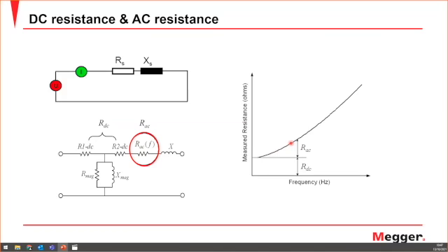That's exactly what happens in reality. If you have harmonics, it will always generate heat, even though you have only one conductor or one joint. At 50 hertz you see no heat generated, but with the higher frequencies you start seeing some heat. And this is because of the skin effect, because when we say harmonic, we mean that we are operating at higher frequency, because the system needs to generate some harmonics due to maybe motor operation or even some loads that will require high frequency currents. These high frequency currents will pass through the windings or any conductor, which depends on its cross-section area. The more frequency you go with this current, you will face higher resistance due to the skin effect. And I have an example here,